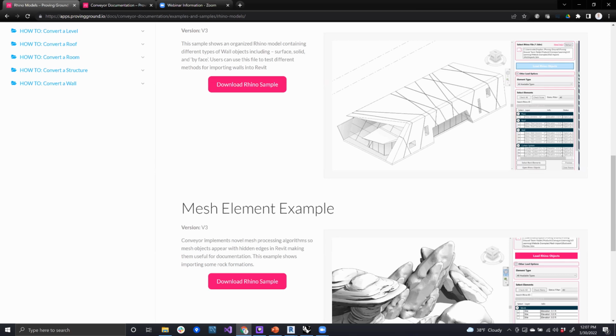Let's see. There is a question. Oh, yeah, go ahead, Nicole. I was curious about Kyle's question. If the dimensions are assigned to an imported block family and those families are updated in Rhino, do the dimensions stay attached in Revit? I actually don't know the answer to that. The answer is it depends on what kind of object and what kind of update you've performed. If you've performed a wholesale update to the family, it very well may need to create a new family to keep it in alignment with Rhino, in which case attached dimensions will drop off.